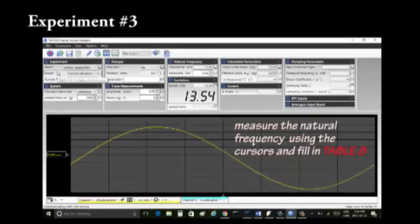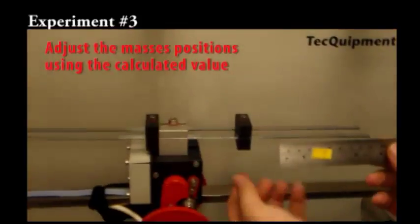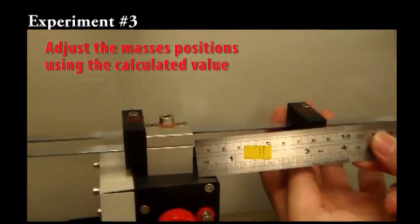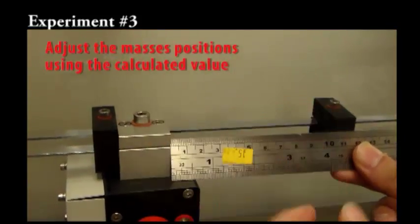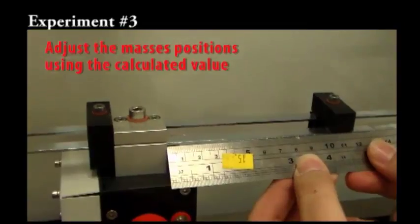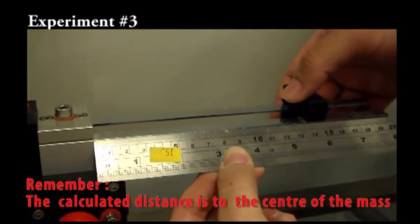Write down the frequency and oscillation amplitude using Table 8. Adjust the masses of the vibration absorber using the calculated theoretical position of the masses to cancel the natural frequency of the system. Remember that the theory calculates the distance to the center of the mass.